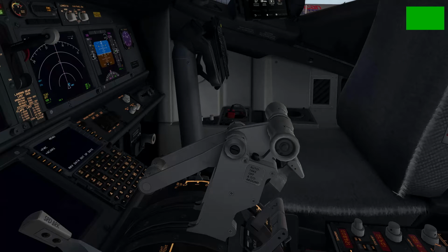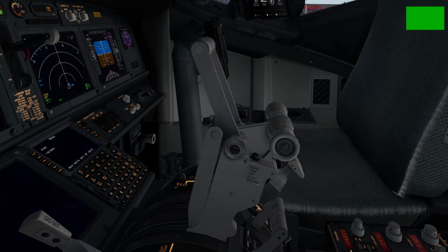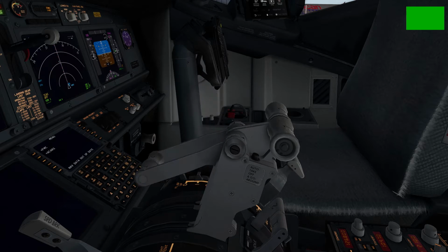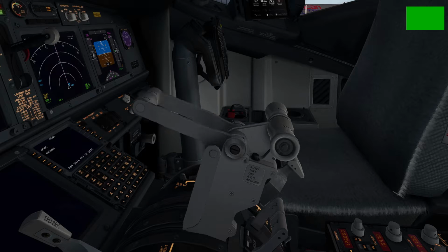If you've ever wondered why, before touchdown, the aircraft goes extremely quiet and then just after touchdown, it sounds like the engines are being spooled up again, it's because pilots turn the engines to their idle speed just before touchdown, and right after the back wheels make contact with the ground, they arm the thrust reversers, thereby accelerating the engines to a higher speed.